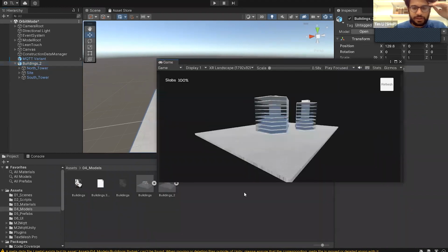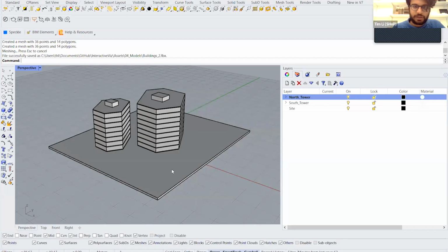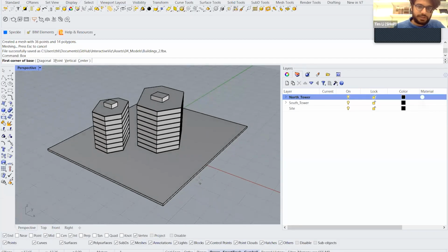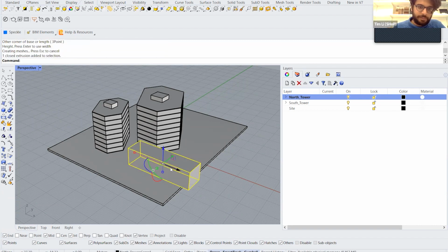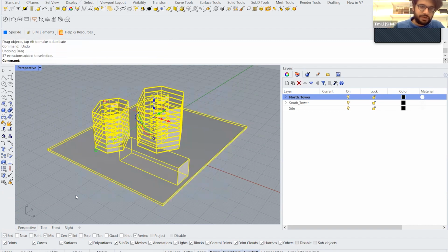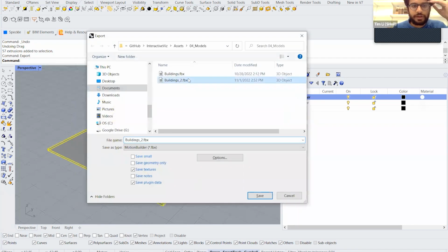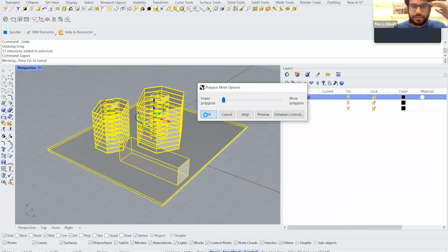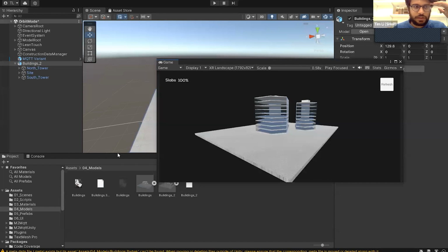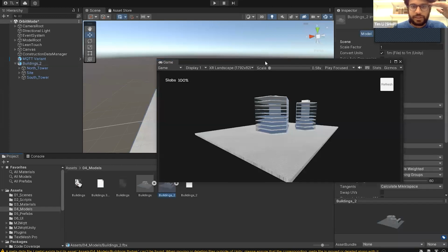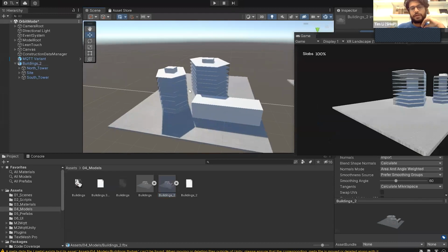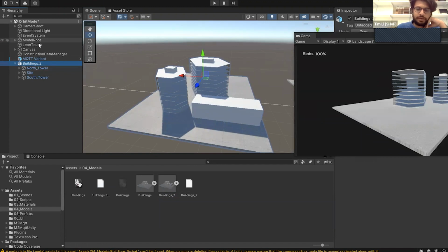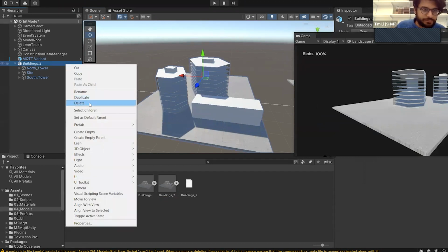And then I guess another thing just quickly to show that's pretty powerful in Unity is if, for example, I added a model to this FBX, and again, hit export, and then overwrote that same FBX. The model updates in real time, and that provides a link between the Rhino model or the exported FBX and the Unity model. But I'll delete that now.